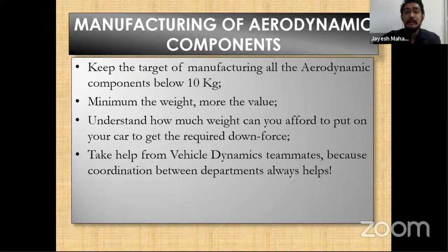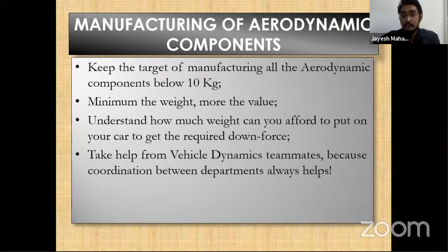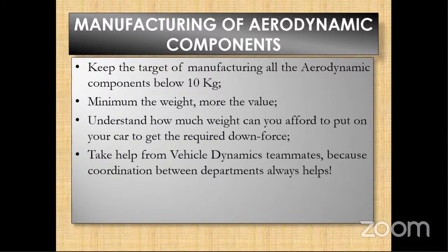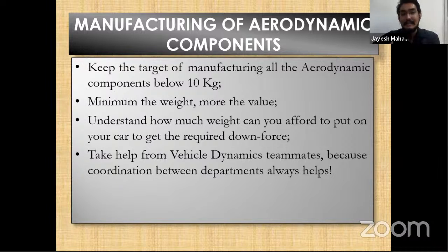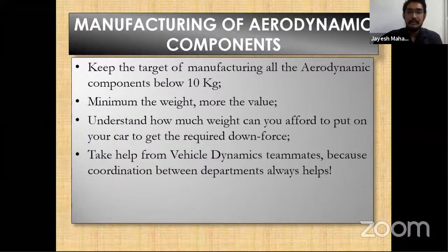Understand how much weight you can afford to put on your car to get the required downforce, and take the help of vehicle dynamics teammates, because coordination between departments will always help you. If the coordination is not that great, then it is not going to work. So take help from your teammates in vehicle dynamics, discuss and understand how much weight you are capable of putting in order to gain the experience. Because in order to increase the downforce, you might end up increasing more drag and putting on more weight, which will actually degrade your performance. So take care of this as well.